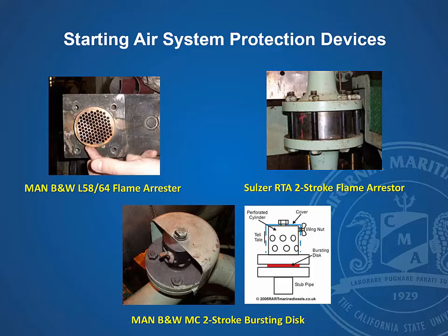So the source of the ignition can be a leaking air start valve, as the hot gases from the cylinder combustion can leak back into the start air manifold, or fuel leaking into the cylinder when the engine is stopped. When the engine experiences a start sequence, the fuel in the cylinder can auto-ignite and travel back to the manifold through the open start air valve. Auto-ignition of oil deposited on the inner surface of the manifold can occur, though I think it's a little bit less likely.